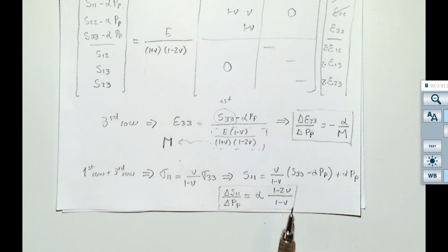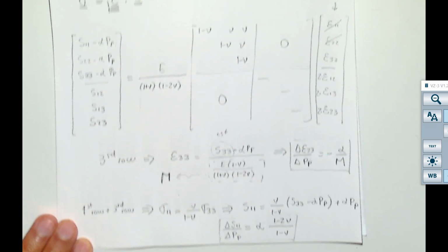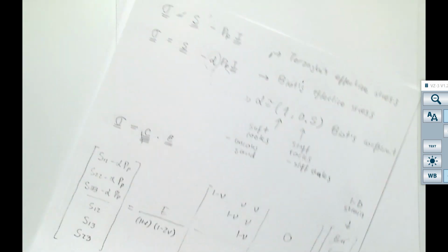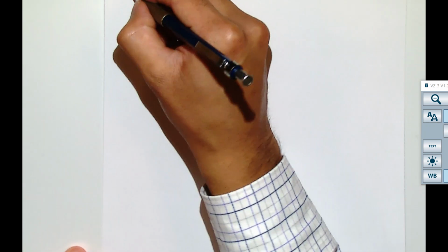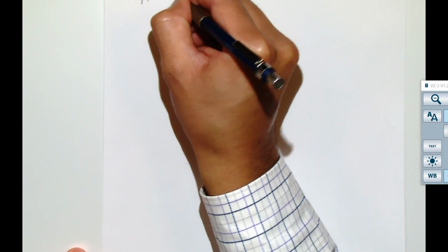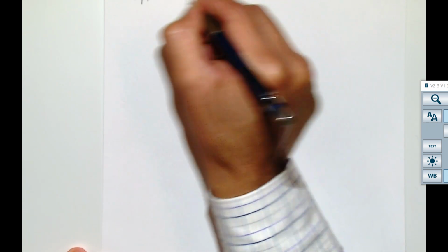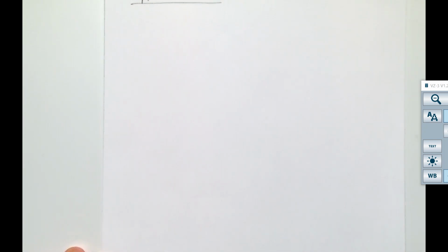However, this one is going to be a smaller number whenever the Poisson ratio is different than 0. And that means that when you start to deplete, you compact the rock in vertical direction, but that compaction in vertical direction makes the rock expand also in horizontal direction. And that's going to make this response different. So with these same equations, also we can tell what is going to be the variation of effective stresses. And I think it's much better to understand first effective stresses and then the total stresses.